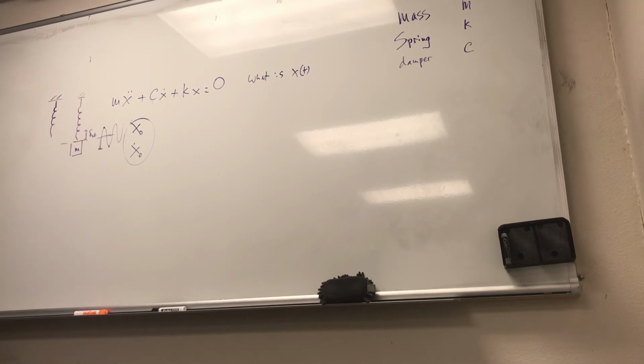This one is fairly clear, right? It's only one mass. If you tell me what x is of that mass, I can tell where the mass is, so it's 1 degree of freedom. How about this torsional system, the disk? Once it has an equilibrium position established, if you tell me how much angle it has rotated, that's enough for me to describe the system, and therefore we need 1 degree of freedom.